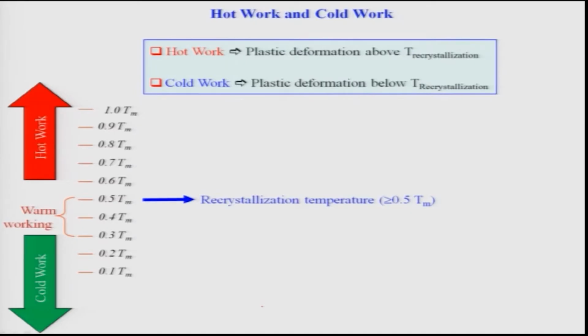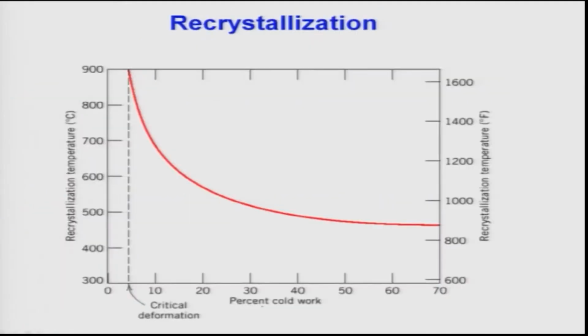So that is the temperature of recrystallization, and this is always true. That means it scales with the melting temperature. For pure metal and alloy, it scales with the melting temperature. That is what you should remember, and this is understandable. It will be clear to you very soon. This is a plot of recrystallization temperature versus cold work, again taken from Callister's book on materials science and engineering.